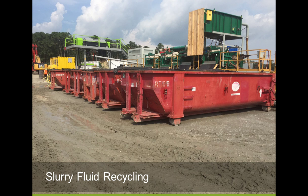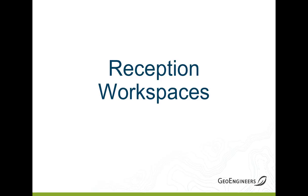So, this is a shot of the slurry fluid recycling. It's similar to what you might encounter on an HDD project with shaker screens and the roll-off bins for the cuttings. Additionally, in the background, you see the ultrafine centrifuge. That's a common sight on a direct pipe project and on some HDDs, but that's something that's pretty common to see.